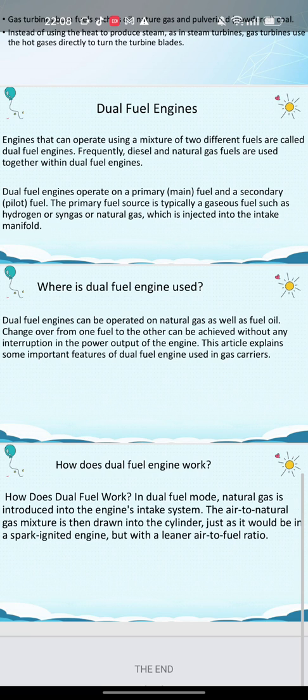Disadvantages of gas turbine: problem of starting. The compressor needs to be operating, thus an external source of power is necessary. Net output is low since greater power is used to drive the compressor. Overall efficiency of the plant is low, 20%, because the exhaust gas still contains heat. Only efficient in a combined cycle configuration. Temperature of the combustion chamber is too high, thus resulting in a lower life.